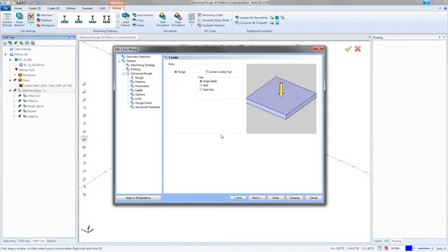And the reason we do this is now we're going to try and start the tool off of the part. This is important because if you set up a boundary and you didn't give that boundary an area where the tool could plunge off the part, it could potentially screw something up, or it could try and plunge into a part without the right tool. But if we tell it that it is a center cutting tool, then we get our ramp options. So you can do a line, a spiral, a zigzag, or a profile. The automatic option is going to pick one of those 4 ways and cut it.